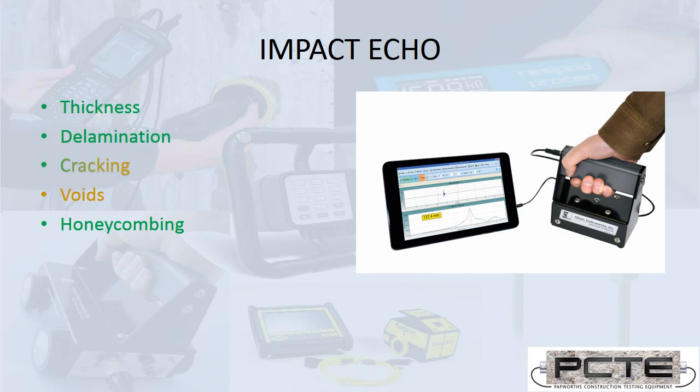It's a useful tool for finding delamination, especially where the delamination has separated two sections of concrete, the thickness will change markedly on the measurement. Cracking, it's okay at. It's quite useful for finding large areas of cracking, heavy cracking through a structure. It's also good at finding cracks that are perpendicular to the face of the concrete, so more like a delamination or angular crack. If the crack is parallel to the surface of the concrete, I do apologise. So it's a useful tool, but needs to be applied with care for cracking.